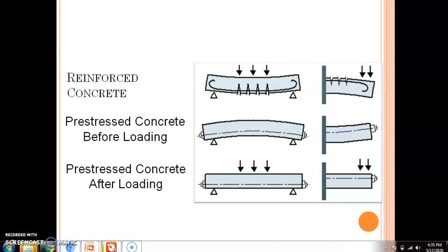If we properly design a prestressed concrete structure, we will be able to design any element which is free from tensile forces, because it's all concrete and concrete is weak in tension. So if we somehow avoid tension, the element will be much stiffer and it will hold its integrity, meaning tension cracks won't develop.